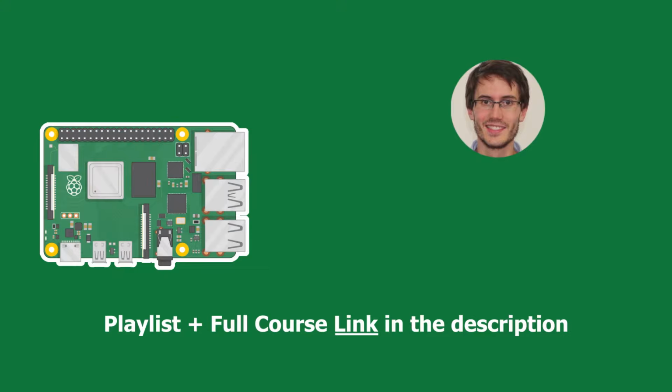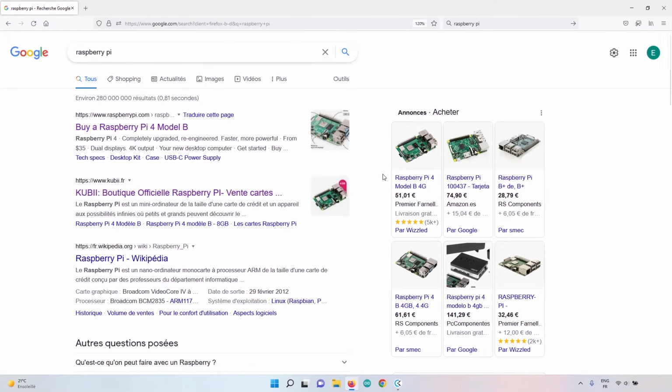And let's get started. The very first step before using the Pi is to flash an operating system on the SD card you have and do some configuration. In this lesson, I will show you how you can easily install the Raspberry Pi OS on your micro SD card, but also how to set up the Wi-Fi and an SSH connection so we can get access to the Raspberry Pi.